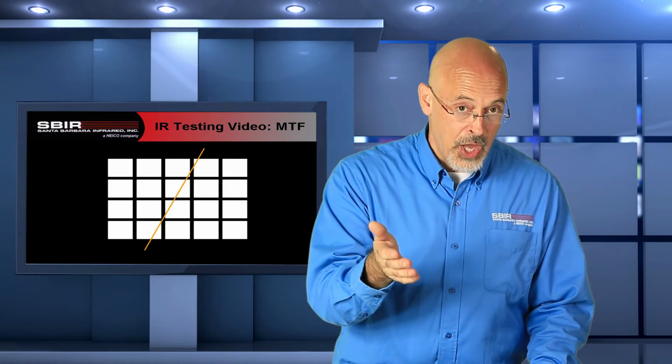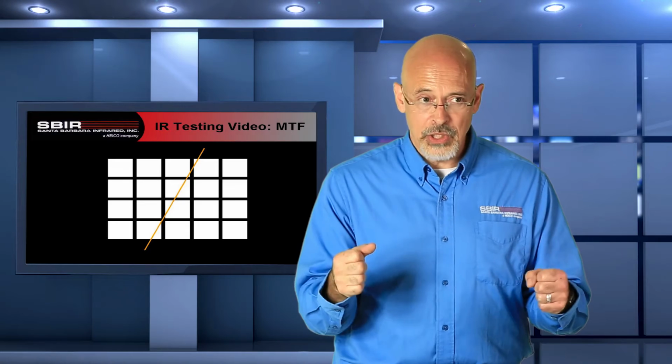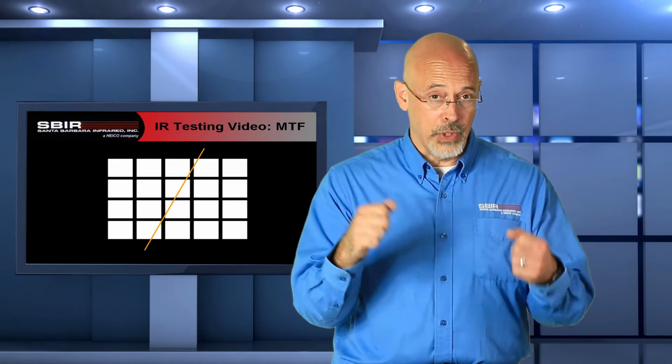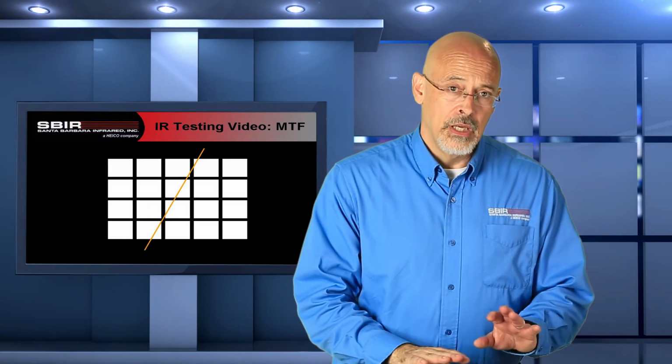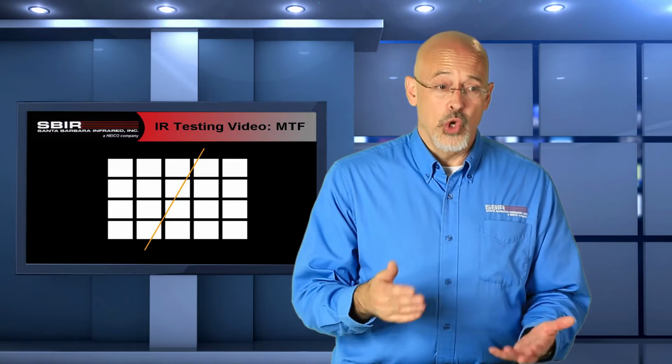What it does is it doesn't give you the most optimum MTF analysis, but it gives you a consistent MTF analysis so that you can go from one camera to the next, or take the camera off the system and put it back in, and you should reliably get the same MTF result. Okay, there are some problems with this edge method. The first problem is noise.